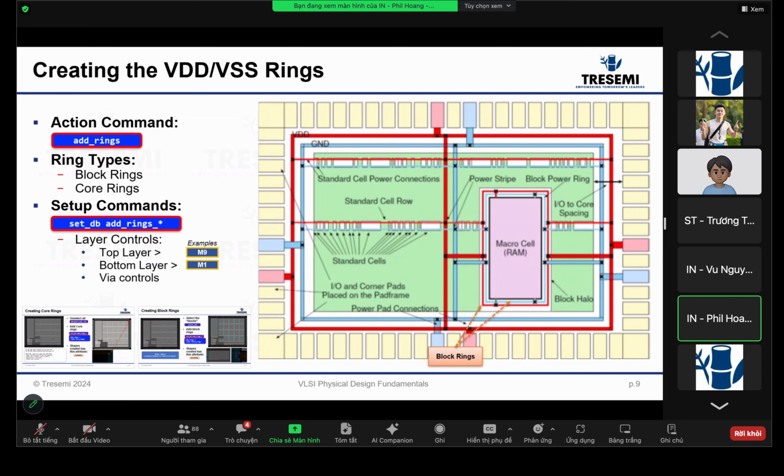But in the past there was some TTL logic that was 0.8 volt, right? So you interface to the very old TTL logic. By that time maybe your IOs are lower than your internal voltage, maybe 1.5 volts, whatever. But in modern ones, I haven't seen it. Yeah, good question. So I can add a comment there.